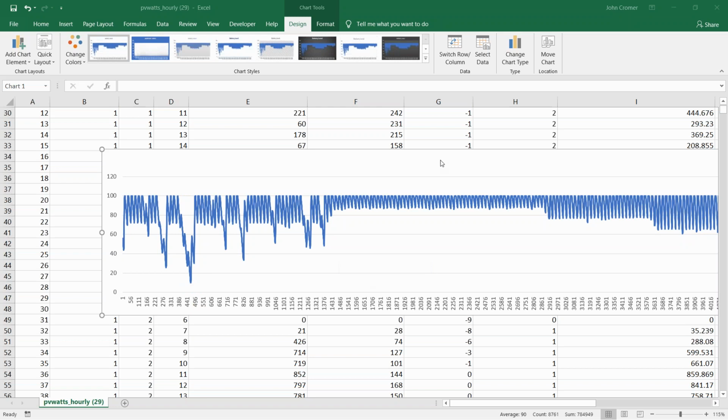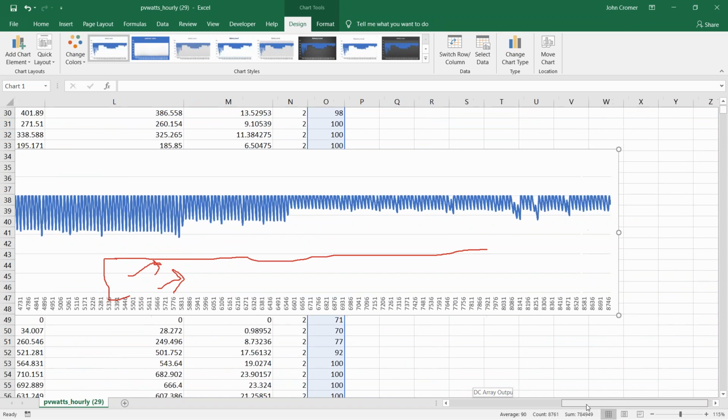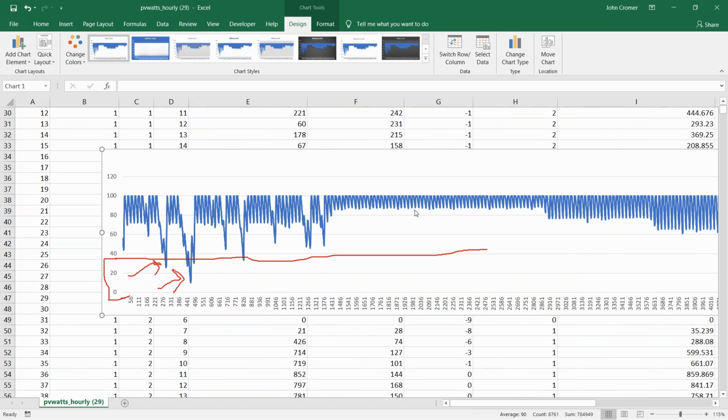And so what I might actually do at this point is say, okay, well, what if we have a 100 kilowatt hour battery bank? Great. You could get away with really not having a generator for this kind of system. But if we did a generator, I would run the generator here, and I would run the generator there, and maybe that would allow us to knock off another 30 kilowatt hours of our battery bank, and just run the generator for a couple of days, and then for the rest of the year we're sitting up at the top for the most part.